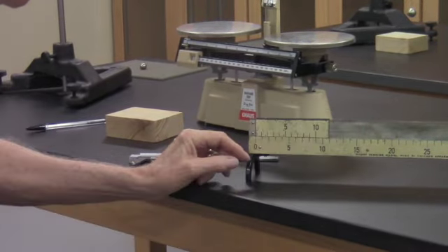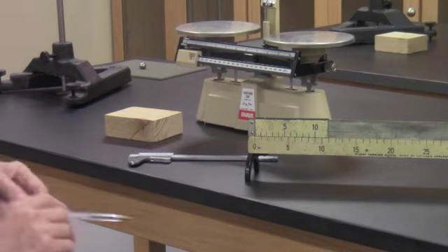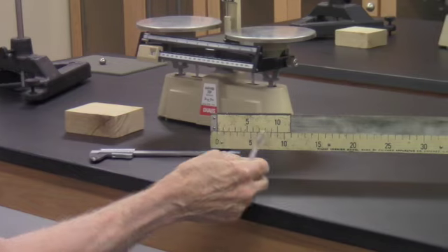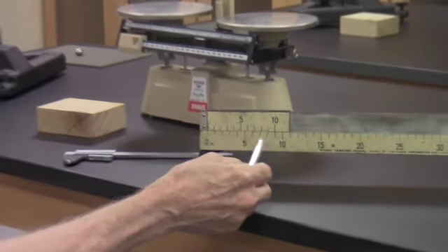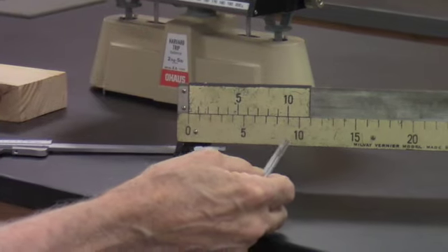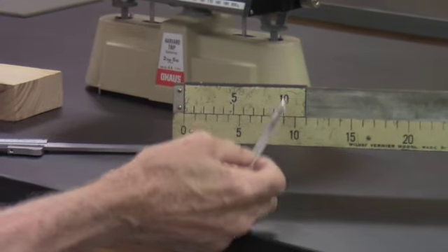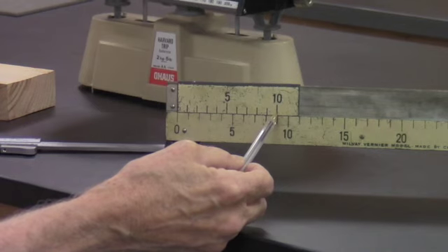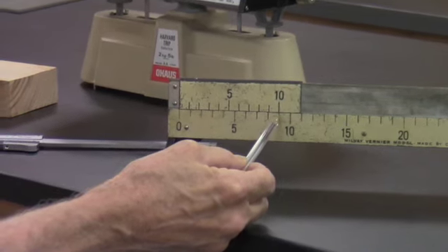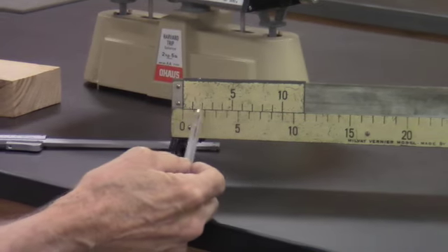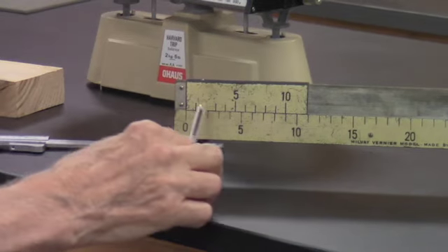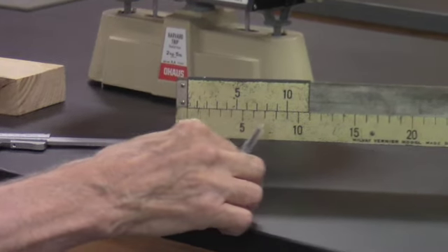So you'll notice that the scale here has 10 divisions, and the scale down here, which is the actual millimeter scale, this is a simulation of the millimeter scale, has also 10 divisions. But this 10 here is kind of hovering over the 9 mark. What that means is these spacings here are basically 9/10 of the spacings over at the bottom here.